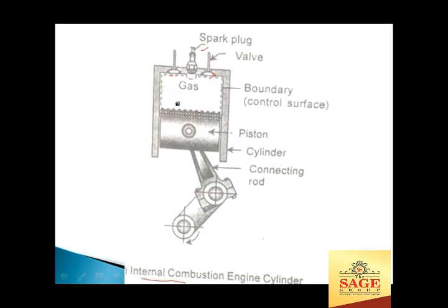So it will produce hot combustion gases, and because of the energy of these gases, it will push the piston, and the piston will move, and then we will obtain some work here at the crankshaft. So the energy of the fuel or the hot gases, that is the heat energy, is being transformed into mechanical work. But what is happening here? There is the entry of the air fuel mixture, that is some mass, and from this exhaust valve, the hot combustion gases, after producing the work, will leave this cylinder portion.